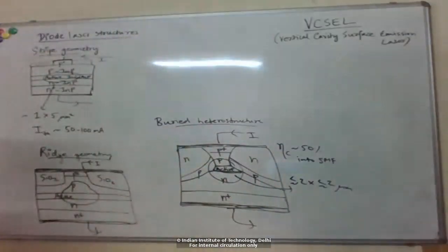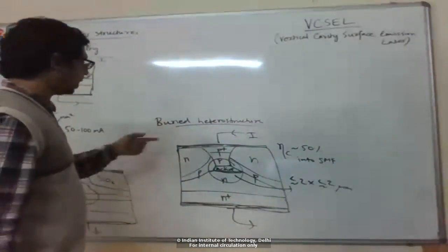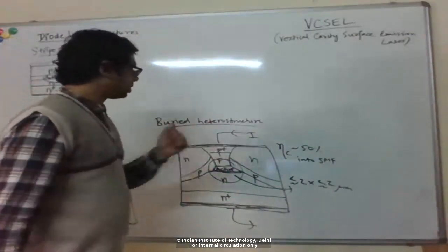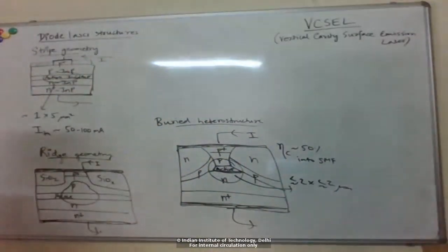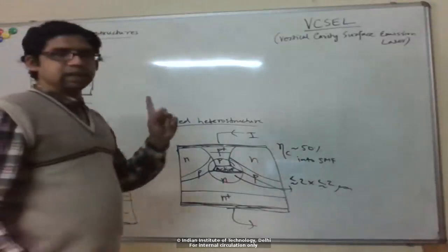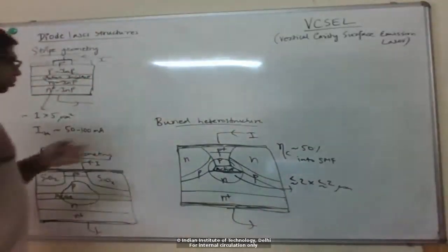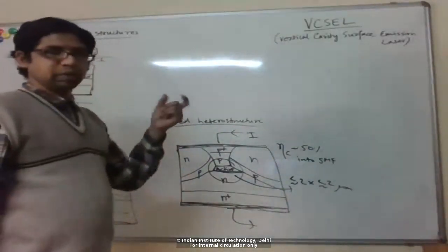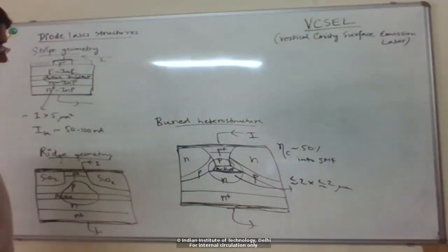Okay, so typically this height is much smaller than the length, right? So we saw like the width is typically maybe 10-20 microns, and the length is like 100-200 microns, right? And that length is basically giving you this FSR or the mode spacing, right? So for a cavity length of like 200 microns, you typically get a mode spacing of a nanometer around in the infrared range, or like a couple hundred gigahertz, right?